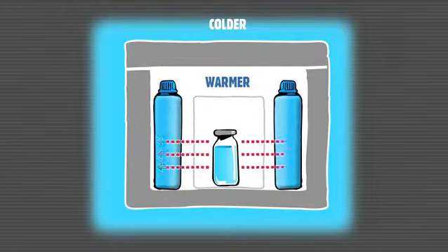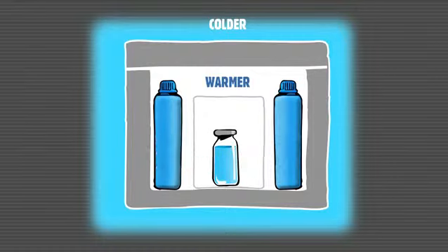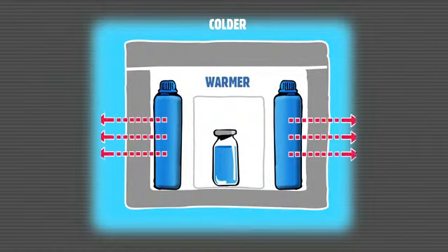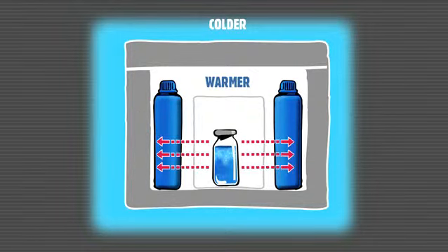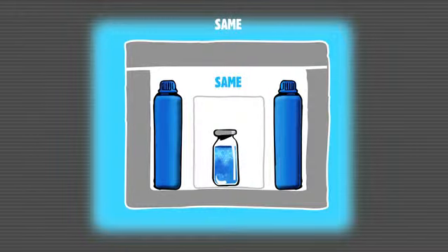Now conversely, if we take a box that has a specific amount of energy in it, and we're trying to maintain a specific temperature, let's say 2 to 8 degrees C, and we put that into a colder environment, let's say a refrigerator that's at 2 degrees C, or into a freezer, what happens? Well, we know from the basic concepts of heat transfer that heat moves to cold. So if it's now warmer inside the box than it is in the surrounding environment, then the heat is going to be taken out of our product and out of the package into the atmosphere. What happens? Our product freezes.